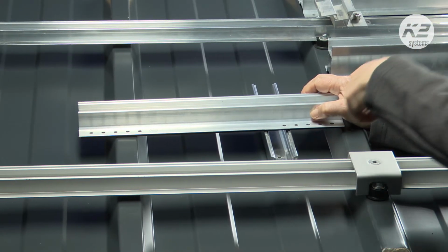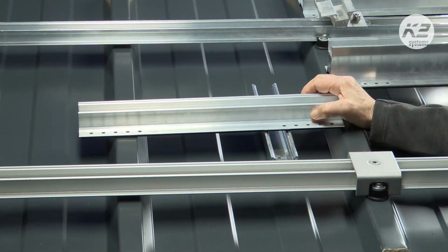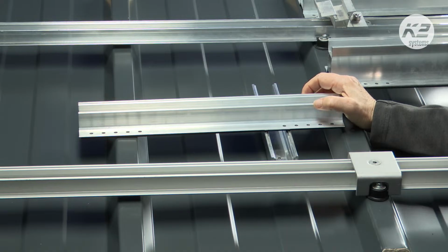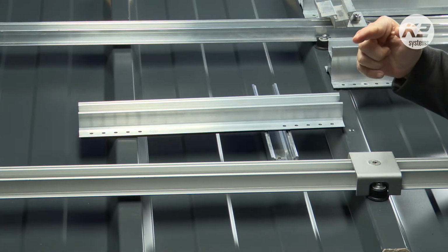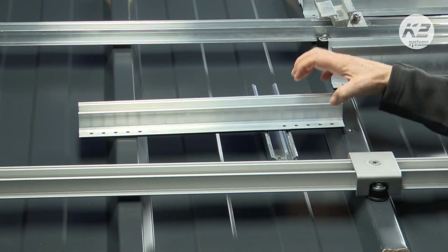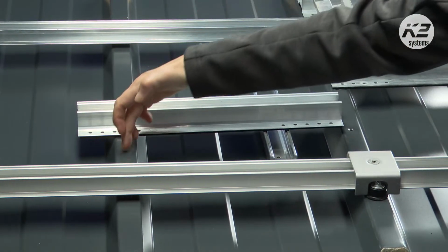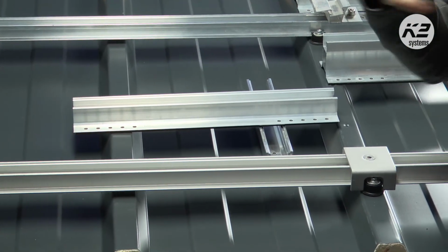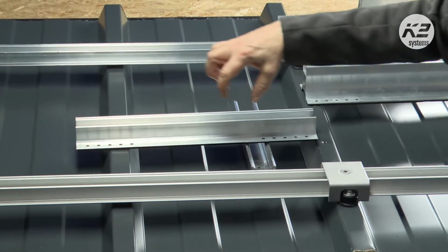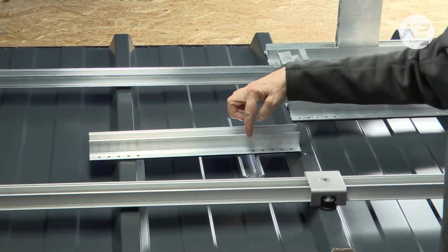Ronnie, once more, maybe you can show that in Base. If you do a MiniRail calculation, it's important that you also enter the width of a crest, because Base can calculate what minimal width you need so that you can use MiniRail for that special combination, in that example or that question, of 200 millimeter crest distance.